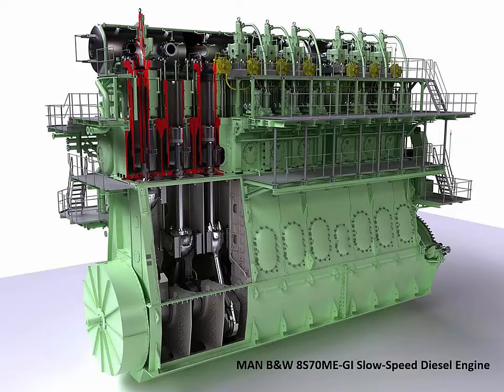So the propulsion and auxiliary diesel generators are started by the timed injection of high-pressure compressed air directly into their cylinders. For propulsion engines, regulatory requirements dictate that sufficient air must be stored to start the engine in a minimum of 2 receivers without recharging. All right, so what we're talking about here is redundancy. You can't just have one start air receiver, because if that became damaged, you'd have no way to start the engine. So there's a minimum of 2 receivers, and for these big engines, you may see as many as 4 receivers because they are so large.